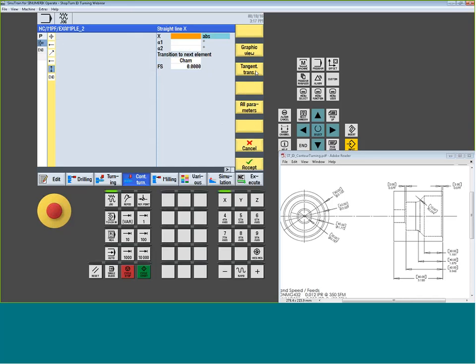We're going to come down to my hole size, which is 0.787. We do have a little chamfer there of 0.079. Now, I drilled it with a 3/4. It's finishing at 0.787. So I need to get into this hole and do something. So I'm going to now pull into the hole. I'm going to go back to the minus 3.150.